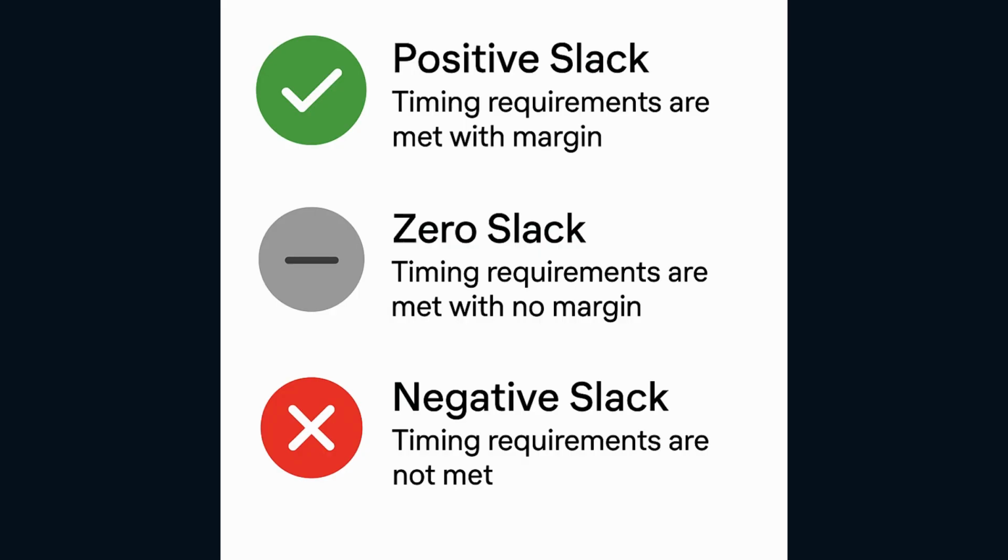So a chip designed with zero slack might work sometimes, or fail intermittently, or only work reliably if you run it slower than intended. It's generally unacceptable for mass production. So aiming for some healthy positive slack is really the goal, not 0 and definitely not negative. Exactly. You need that positive margin for robustness and yield. Too much positive slack might mean a path is over-designed and could perhaps be optimized for lower power or smaller area, but some positive slack is essential. Negative slack is simply failure.